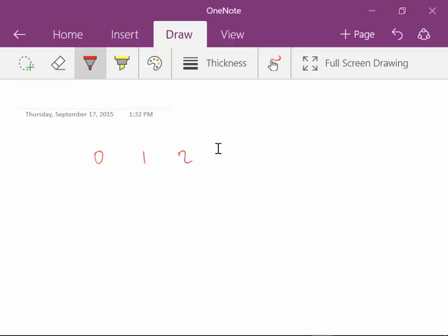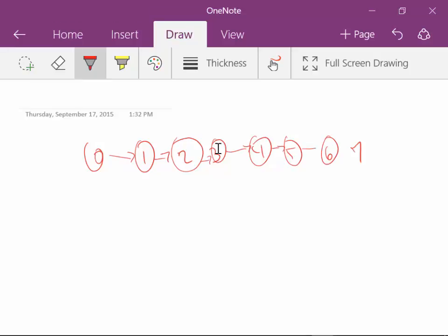0, 1, 2, 3, 4, 5, 6, 7. A counter is a finite state machine. Now, in the case of a counter, there's a 3-bit up counter that recycles. There are no inputs. The only input is a clock. Now, an ideal finite state machine will change states only on leading clock edges. So we're in one state, and we go to a next state.